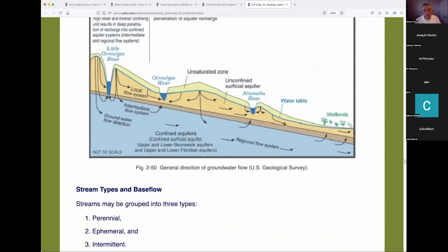The difference between surface water, meaning the water that runs on the surface, and the groundwater is that both of them are diffusing, but they're subject to different diffusion equations. The diffusion of the groundwater is very strong, so most of the peak is gone, and it all comes out as very mild flow. The diffusion of the surface water is very weak, sometimes it doesn't even exist.